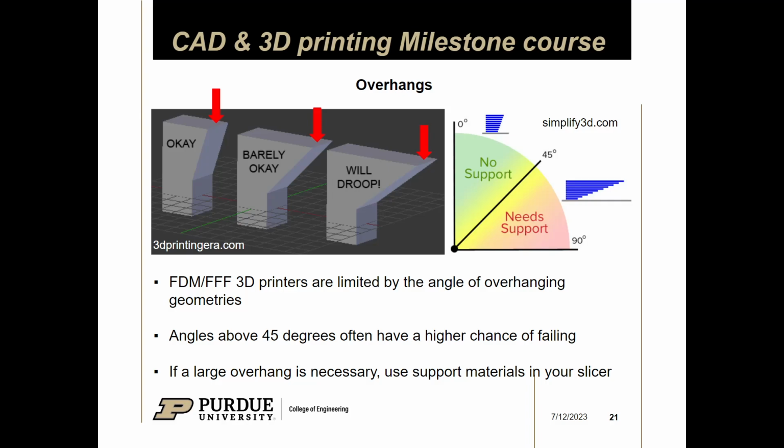The middle one is getting there. It's pretty tough. You see, it's a 45-degree angle. And then on the far end, it's probably like 30 degrees. And that's when you want to start to worry, or you might start thinking about supports, right? So generally, when you're modeling, 45 degrees is a really good, safe number when you want to make something angled, right? Yeah, 45 degrees. If you have anything more than that, it'll start to droop.